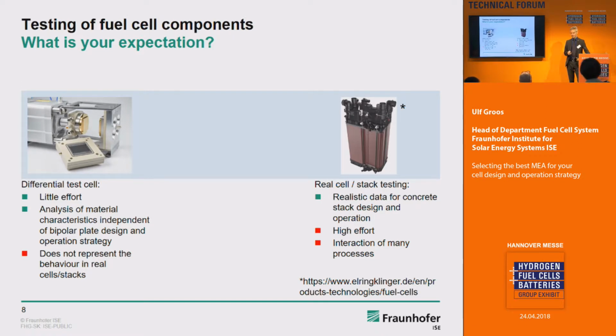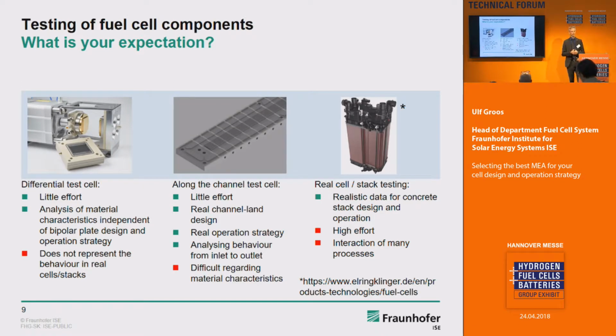What we propose is our so-called along-the-channel test cell. This is a test cell which has a small active area, so it's little effort regarding the test bench, little effort regarding the operation and consumption of gases, but you still can use your real channel-land designs which you have in your stack, and you will operate this with your real operation strategy, so stoichiometry, humidification of the gases, which reflects your system operation.